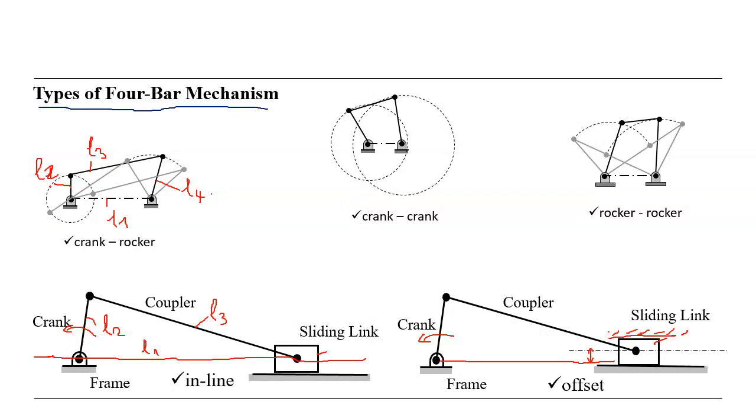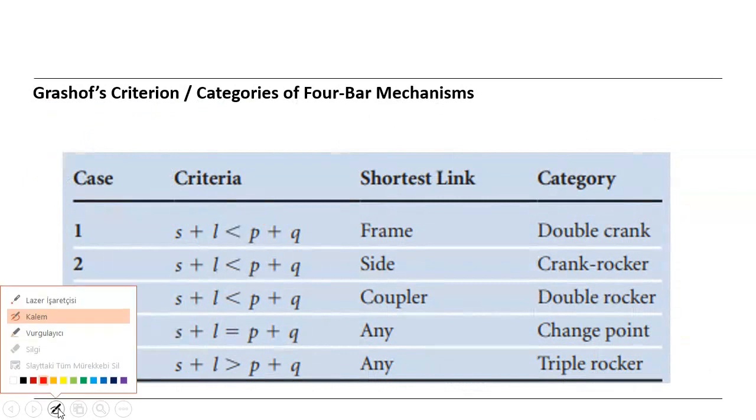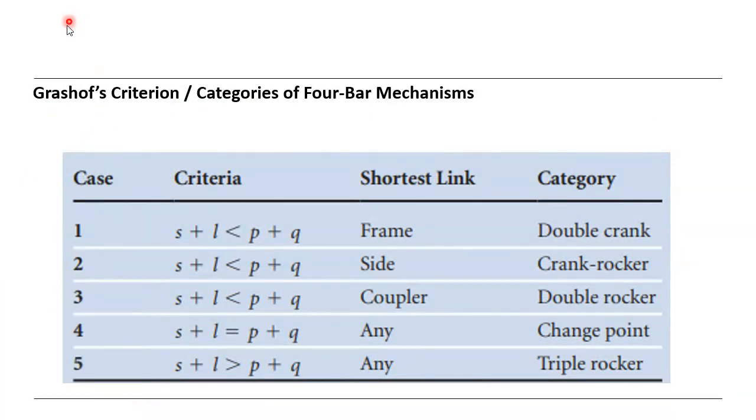Regarding these lengths of the links, we can make some definitions according to the Grashof criteria. Grashof is the person who did research on this. There are 5 cases.